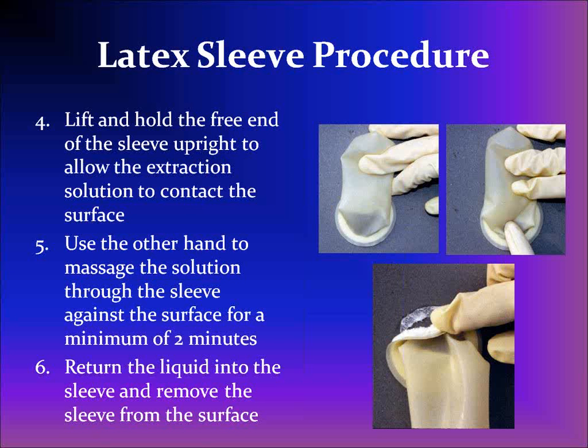After removing the latex sleeve from the surface, place it through the hole in the kit box lid with the open end of the sleeve up. The sample will remain in the bottom of the latex sleeve.